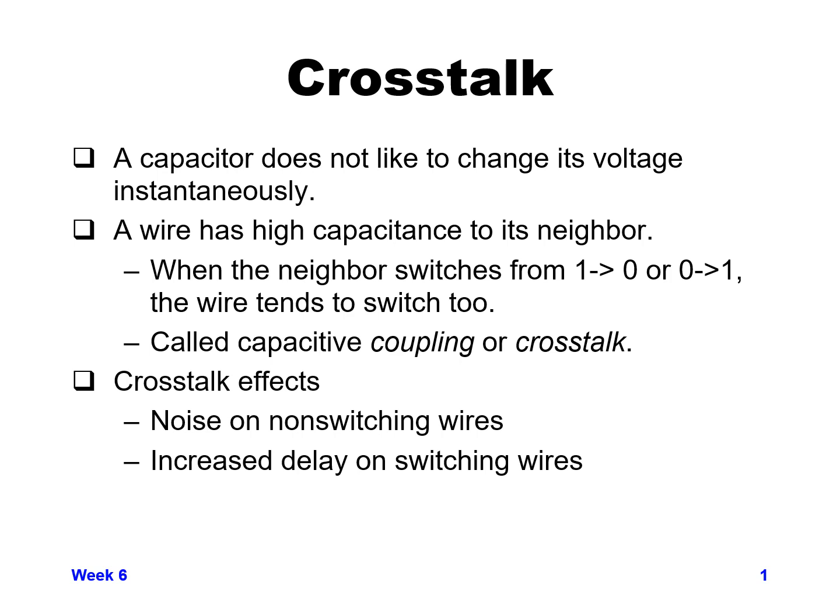And so this increased delay needs to be modeled correctly, otherwise you'll get the wrong delay calculation, and you'll think that your circuit is faster than it is in reality. So crosstalk is very deceptive in some ways, and can be difficult to model and difficult to prepare for if you're not aware that it's happening.